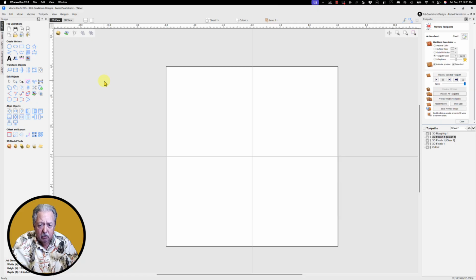In the example we just discussed, coming from Vista Sculpt, I had the frame around it, so it made it very easy for me to take that Rhino picture and turn it into something that I could carve. The limitations in vCarve are that you can only have one STL. So my recommendation is that if you are going to import something from Vista Sculpt, you want to make sure that it has as much detail in it as you want in vCarve. Otherwise, it's going to be just like any other component that you have in your clip art library, except that you can only use one.